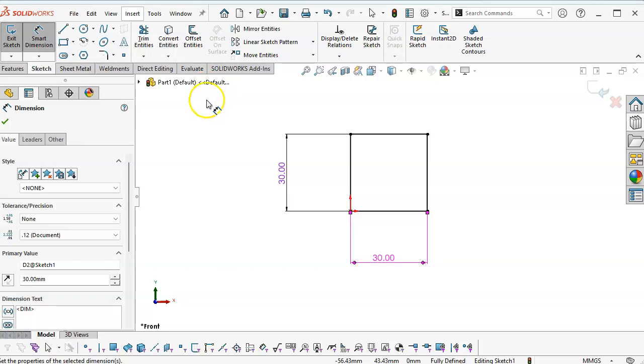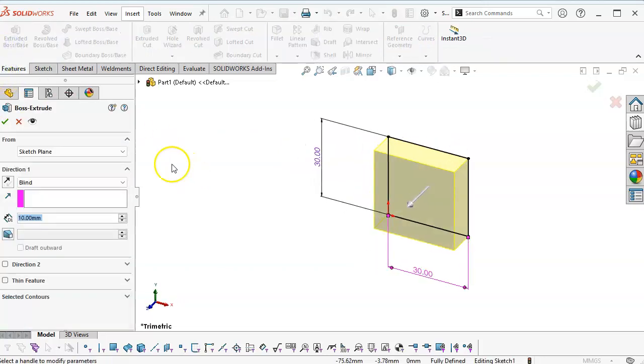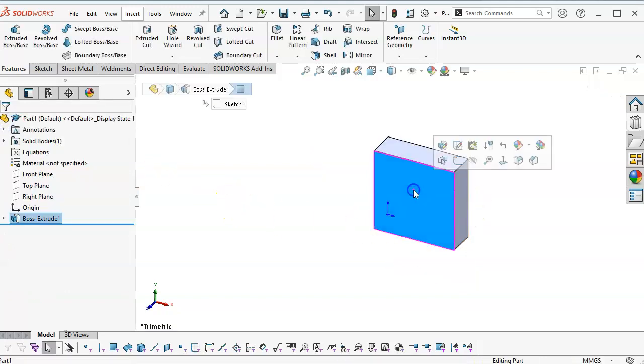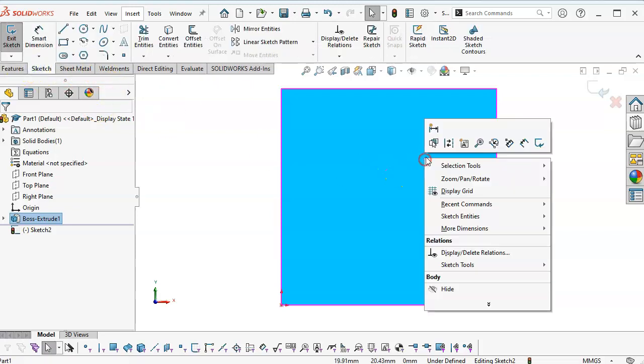All right, so this is 10 millimeters thick. I'm thinking that I want this to be a separate feature so I can manage suppression states, I can do other things. So that is where design intent comes in. Even though I could, my future decisions say that it's going to be better if I go ahead and extrude this, and I don't particularly care which way. So 10 millimeter. We open up the next sketch, and because this has the potential to shift, let's see.